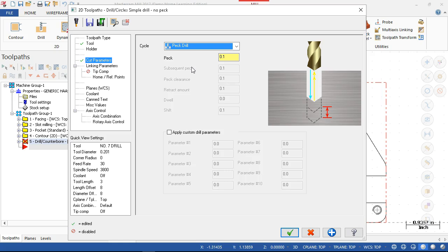Okay. Second question on the reamer: if the hole is all the way through, how far does the reamer have to go past the bottom of the hole? Technically, past the chamfer. The lead chamfer on the reamer should go past the hole. Depends on how much wear. If you've run that reamer a couple hundred times and you're starting to get a little wear on the tip, probably needs to go a little further, or it's time to grind it, push it back a little bit, pick up fresh fluid. And so, you'll observe by putting the gauge pins in and saying, wow, that hole's not quite to the same tolerance as it was on part 1 at part 500.